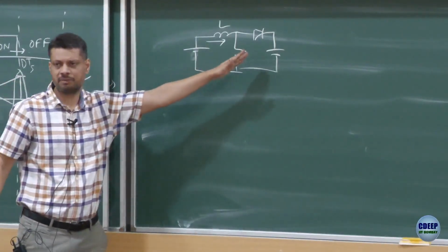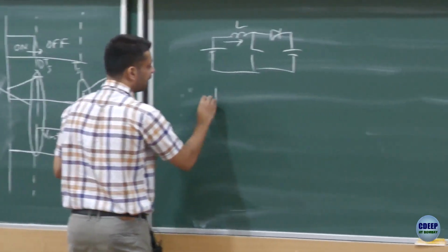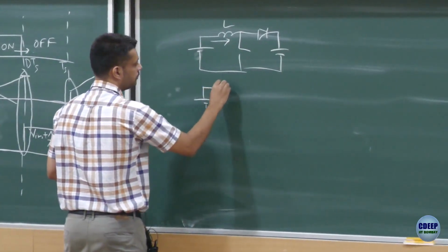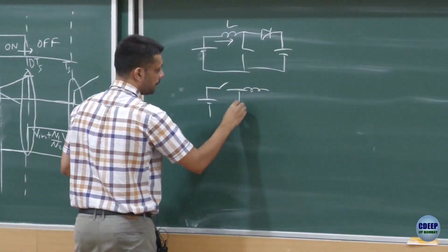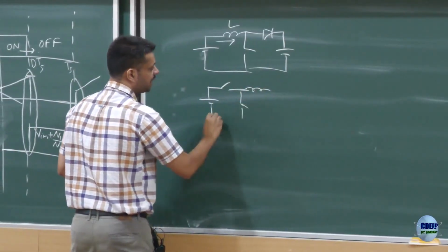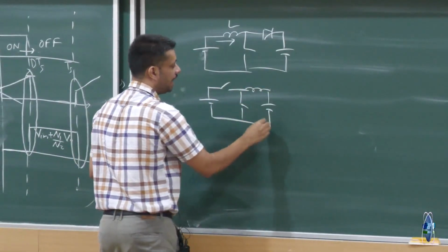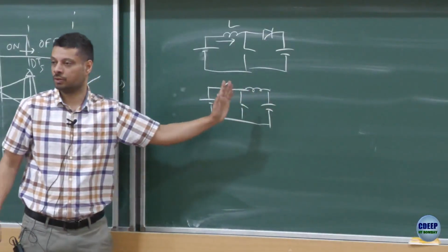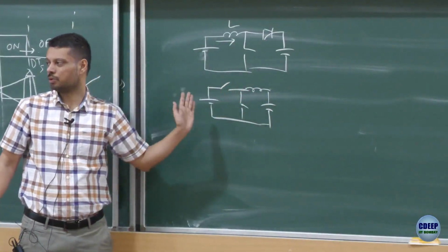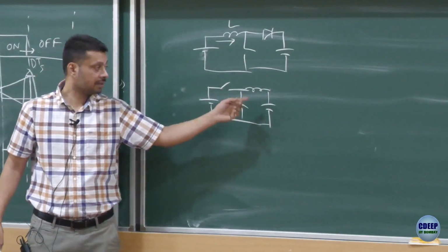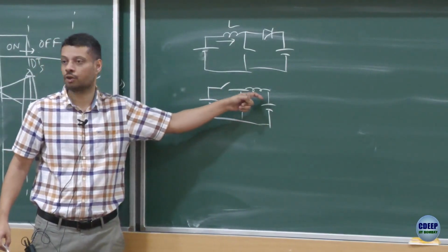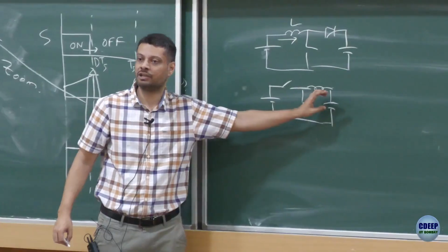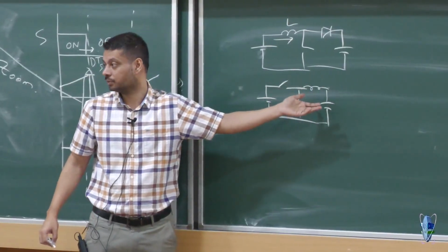The output current ripple will still be there. If I use a buck converter, then my output current ripple will be almost 0, right? The input ripple will be there. The current ripple going into the capacitor is almost 0, so even the smallest value of capacitor would work out to be fine for you.